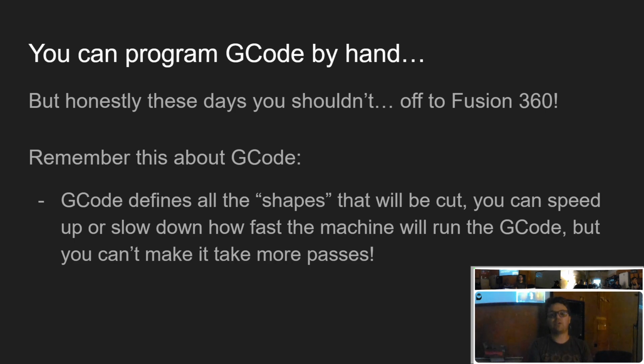But there are a lot of them. When you get out into the professional world, I think a license of Mastercam is like $20,000 these days. And there are reasons that companies pay through the nose for these, because if you're a professional machine shop, good G-code can run a part literally 20 times faster than bad G-code. The amount of value that you get out of a production CNC machine is driven a lot by how good the program for that machine is at making a given part. They care massively about how fast their people can set up a part and how well the machine will run that part with that code. So little optimizations they pay through the nose for.